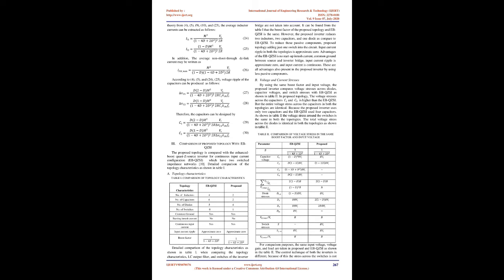D, inductors, and capacitors. Design. During the shoot-through state, the inductor currents rise linearly according to the above operation principles. Therefore, the current ripple of the inductors can be obtained in terms of equations 2, 14, and 15, as follows.